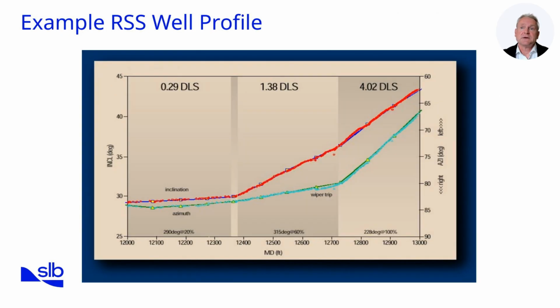This slide presents a real example of an RSS well profile. The image shows a smooth, continuous trajectory, free of spiraling or jagged transitions. In contrast to slide rotate wells, the RSS profile demonstrates predictable curvature and precise control. Looking at the chart, the benefit is twofold. Smoother boreholes reduce mechanical drag, and accurate trajectory placement maximizes reservoir contact. For operations, this means easier casing runs, improved cementing, and enhanced logging quality as tools pass freely in the wellbore.